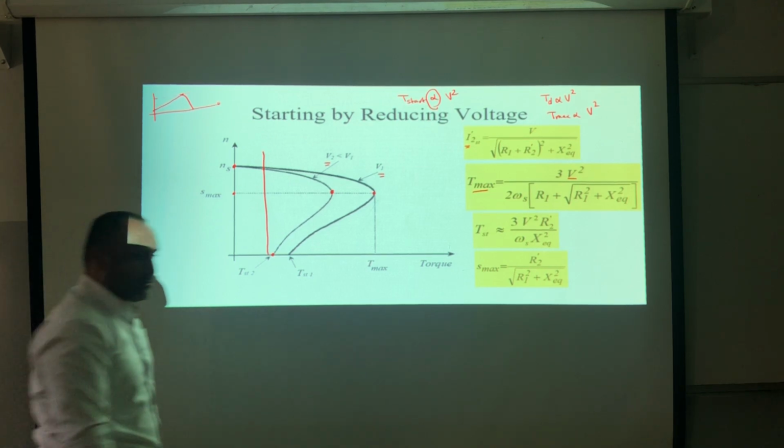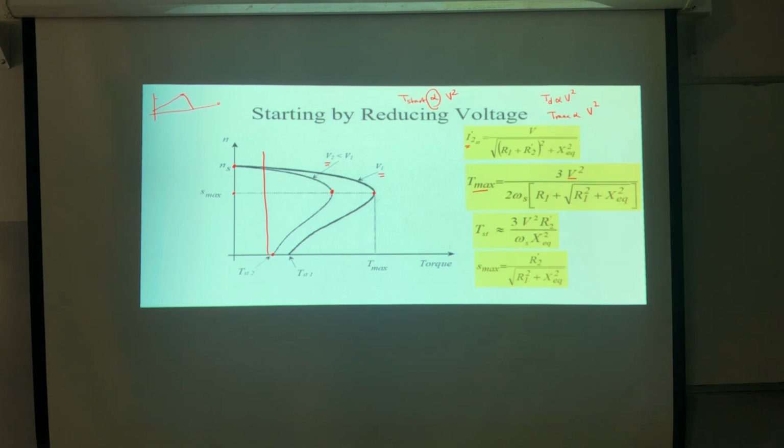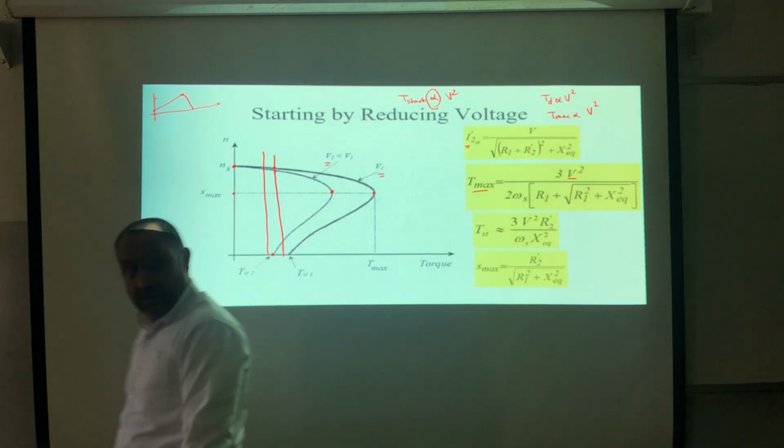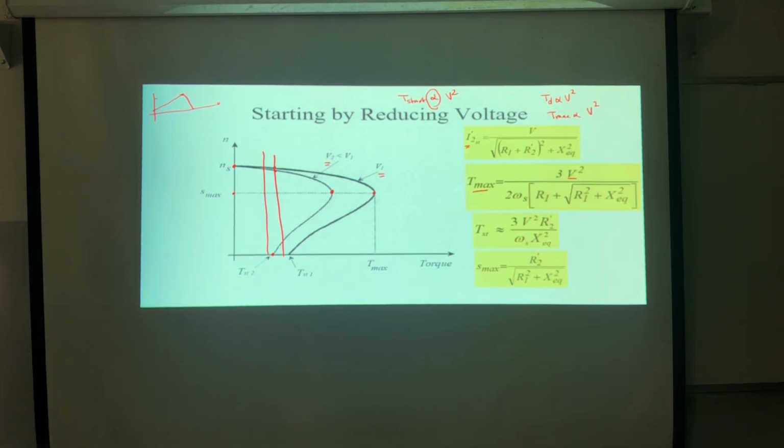The second thing, what about if I'm having the following torque speed characteristic? What will happen? So simply here, if I'm reducing the voltage, I'm reducing the maximum capability of the machine. So simply someone will say this voltage control is restricted. Sometimes we say that you are only allowed to change the voltage between 0.5 of the rated until the rated. And in this case, you will have what? A narrow speed region to control the machine.